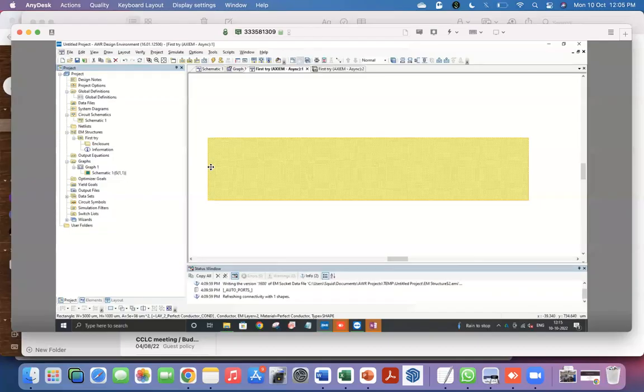And for a microstrip, it's always at the edges, right? And which edge? The left and the right edge, because the transmission line is along this way. I can put the ports here, but then it would be a different transmission line. It will be a 10,000 micron wide transmission line, a width and a length of 1,000 microns.